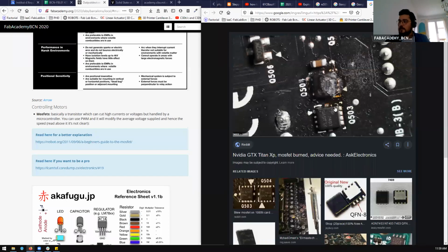And this is something that you might also see really commonly when the PCB is older. A lot of electronic DIY household devices, from vacuum cleaners to others, sometimes have MOSFETs, SSRs, or relays to activate different things. It is actually one of the most common failure points of electronic household devices: MOSFETs, regulators, and SSRs or relays.